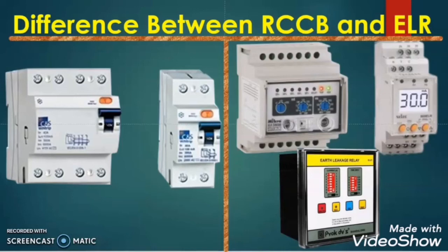Today in this video, I will discuss the difference between RCCB and ELR. The confusion is very obvious because the function of RCCB and the function of ELR are the same. Both give protection against earth leakage fault, saving humans and stray animals from the earth leakage fault current.